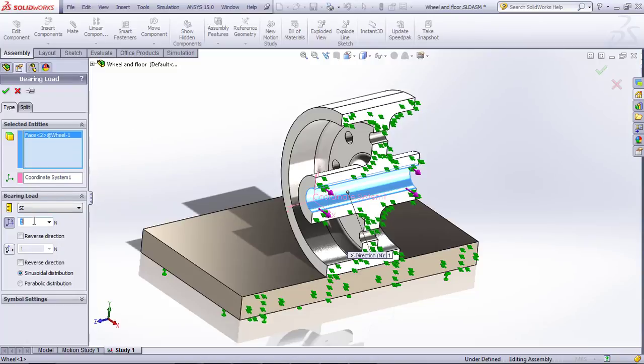And we'll do, we don't want it in the X direction. All right, so you can see where the X direction is, hopefully, slightly, there's the X. Y is up here, so we want to go in the Y direction. And we do 2000. And you can see where the arrows are pointing, so that's the positive Y. We want to go in the reverse direction. And so that's the way we want to go.